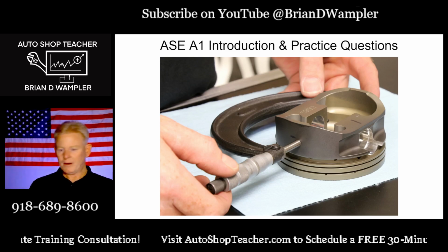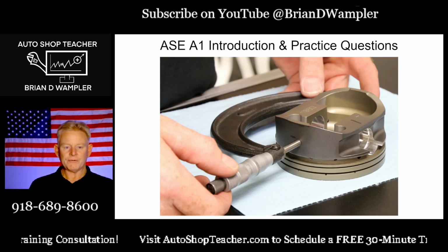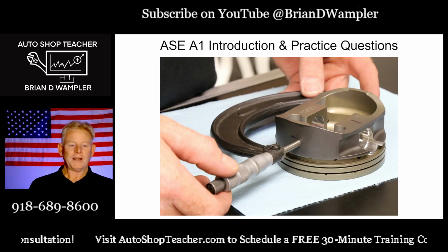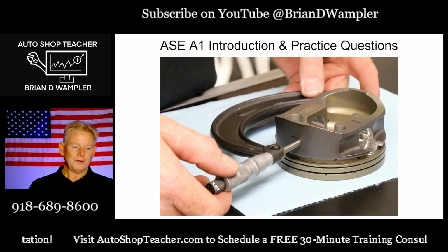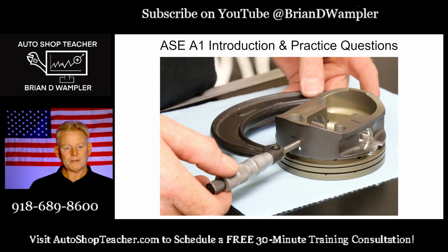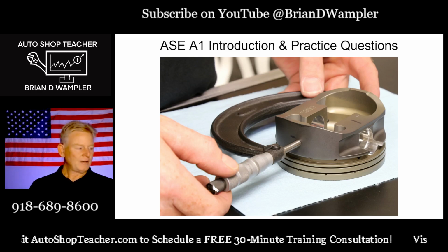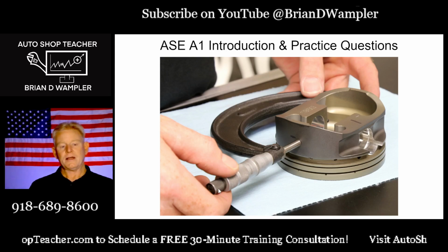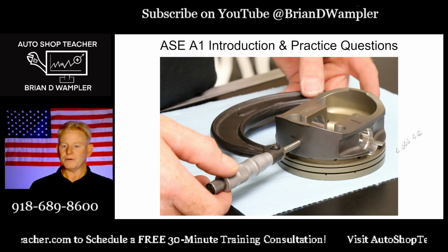Or if you're an 80-pound gymnast or whatever, if you don't have a lot of hand strength, still, you bring down this micrometer until it's making contact with the surface you're measuring, and you turn this thimble to the point where it starts clicking, you're done. That's your measurement, then read the micrometer.